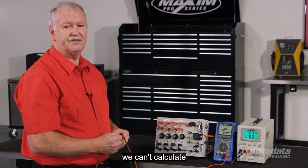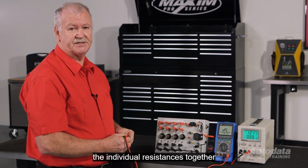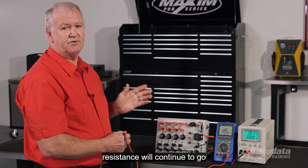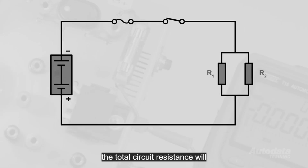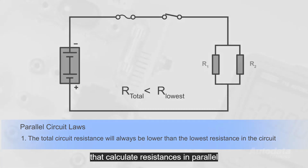We can't calculate the total circuit resistance in a parallel circuit by adding the individual resistances together. In actual fact, if we add more branches to this circuit, the resistance will continue to go down. Rules for parallel circuits. The first rule is the total circuit resistance will always be lower than the lowest resistance in the circuit. There are formulas to calculate resistances in parallel.